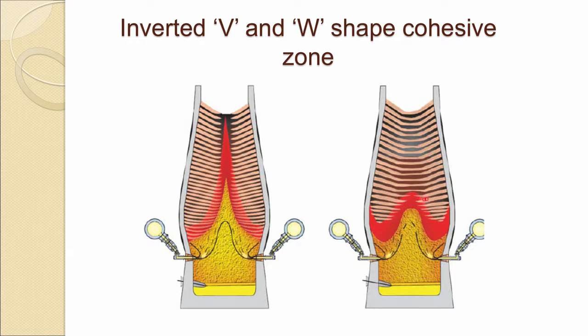So, when it becomes fused, which means the gas cannot flow through that. Already ore has a very low void fraction. So, gas already feels quite a big resistance, and now in this condition where it has fused, the gas cannot flow through that. So, reduction of course becomes a problem, and not only the reduction, main thing how the gas has to flow. So, that is the reason you have to maintain this layer thickness of the coke.